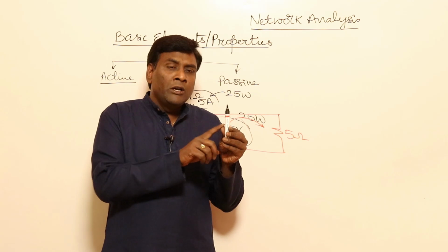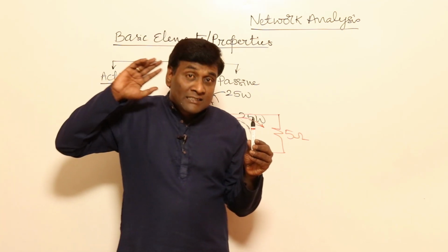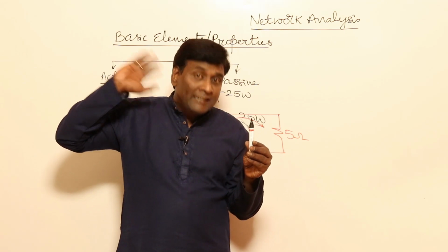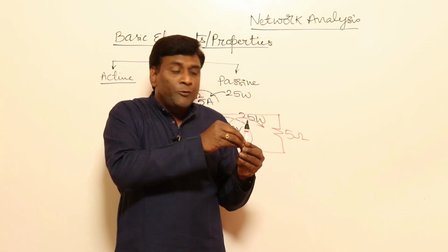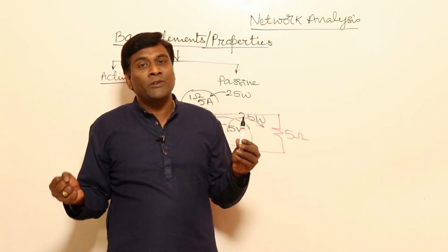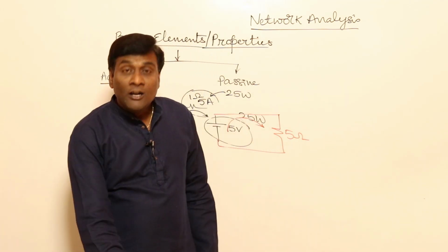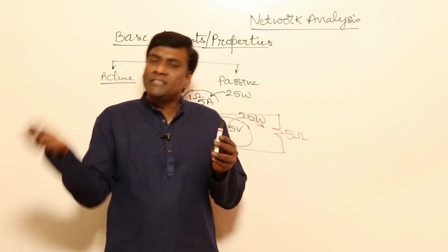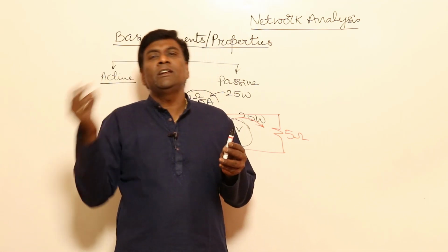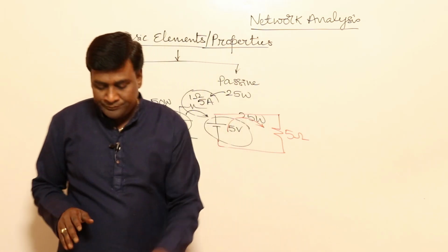Okay. So maybe now, or maybe somewhere in the history, at minus infinity, you might have stored electrical form of energy. And somewhere in the future, you are going to take the same electrical form of energy. So from minus infinity to plus infinity, if you take how much is the total electrical power delivered by this? 0. Because it is taking electrical power only and it is giving electrical power only. So inductance and capacitance cannot be active.